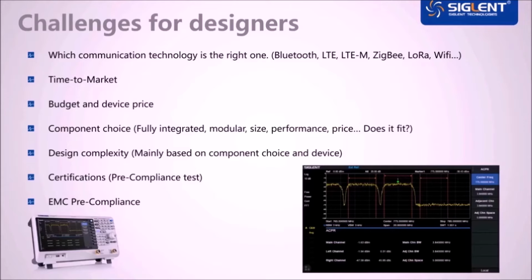First, we have to decide on a communication standard. If you want to integrate your device into a smart home, then choose Zigbee or Z-Wave. If your device has to work anywhere in the world, it might be LTE or Extended Coverage GSM for IoT devices. There's also a fair chance that your device needs multiple interfaces.